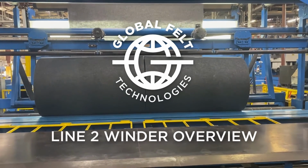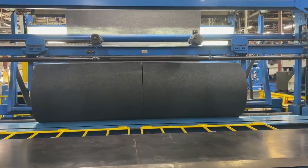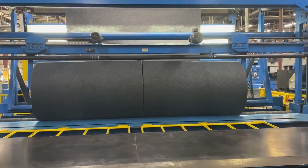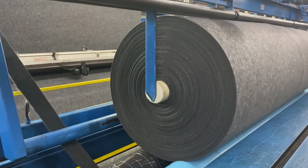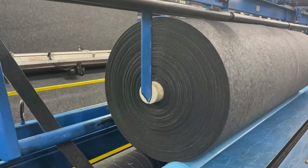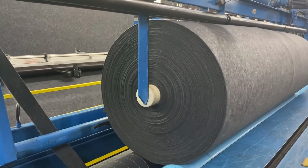In this video segment, we will learn about the winder and its importance to the needle punch process. The winder is the last step in the overall process of forming a needle punch product. On the winder, the fabric will be rolled up on a core and will be described in terms of fabric weight, width, and length of the material on the roll.